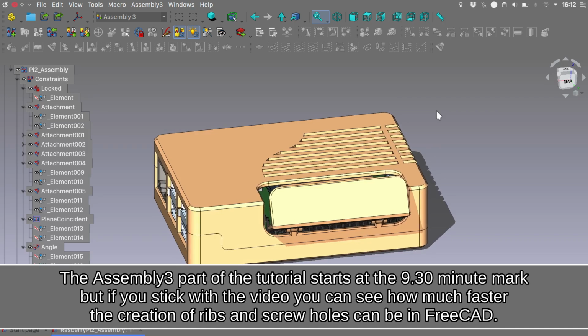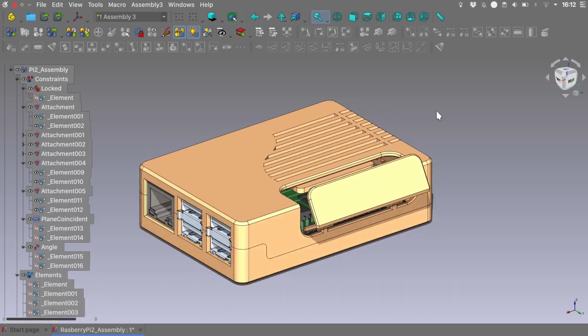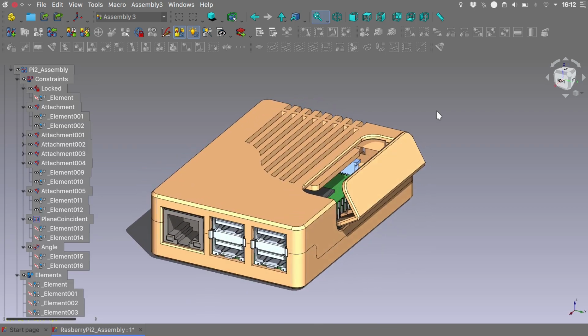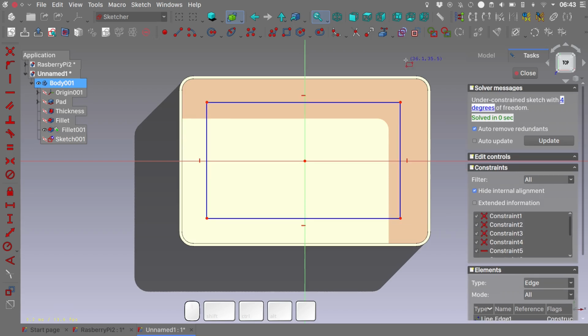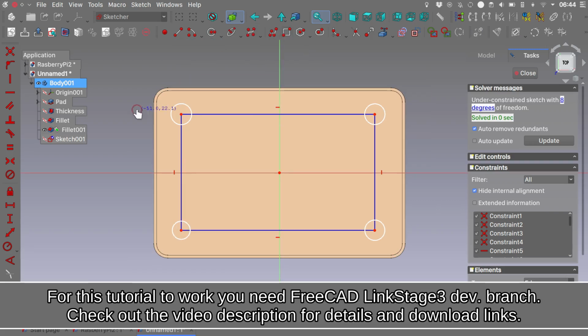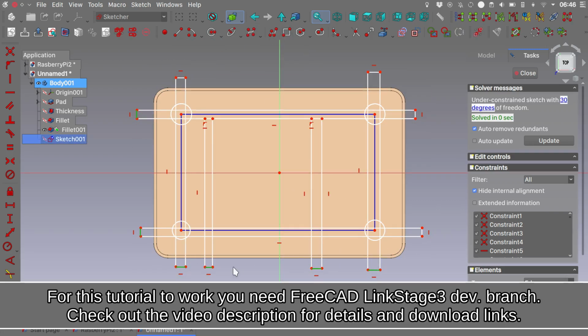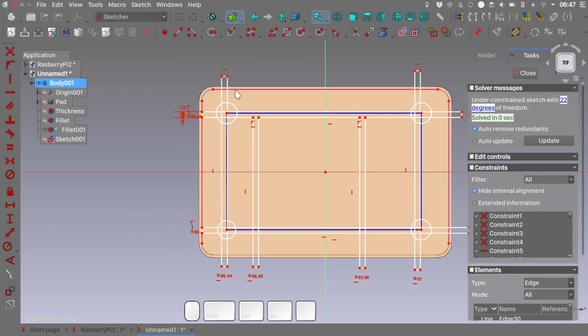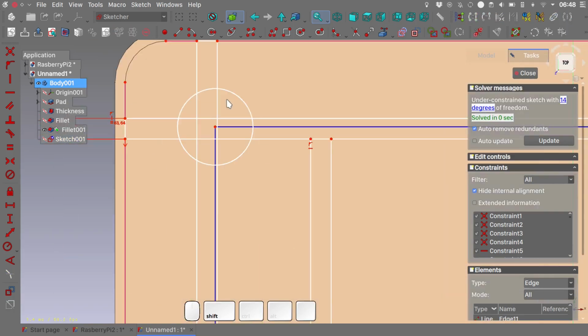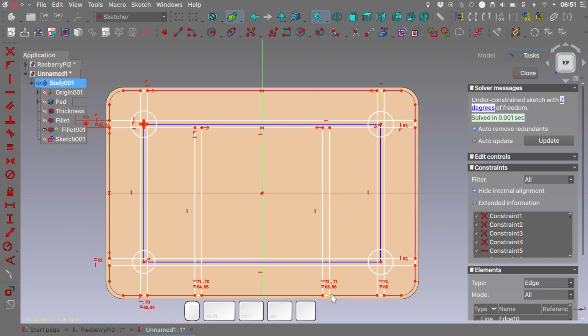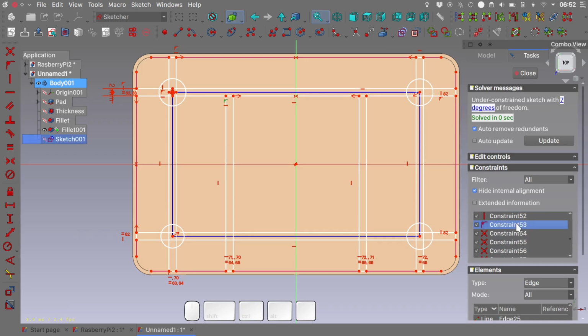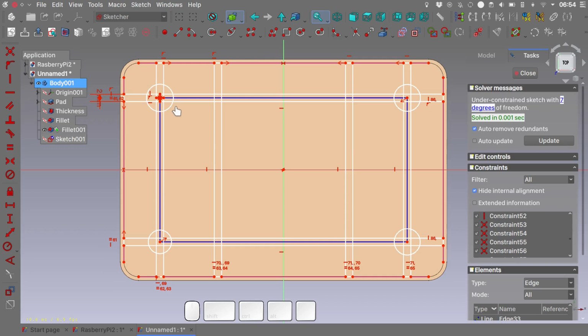This technique can become a huge time saver in certain workflows where we need to model, for example, ribs or other intersecting geometry. So just to have an idea of how things work, let's open the sketch, and while at least having a vague idea of what we want to model, let's start drawing some ribs geometry. So notice how I haven't bothered to construct a clear outline of our ribs, and I've only used simple rectangles to create an outline.